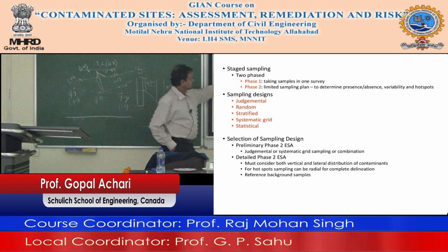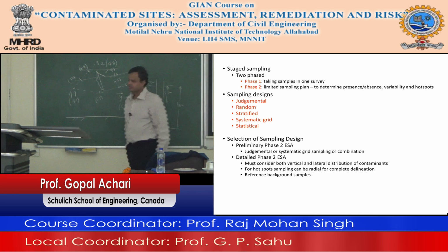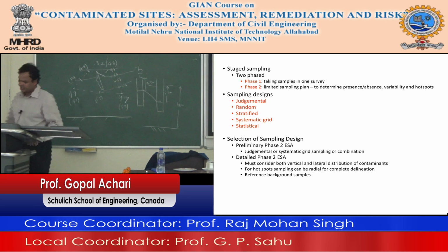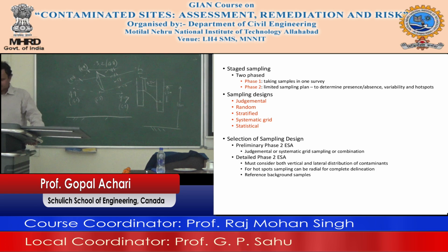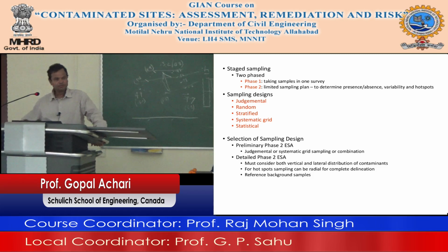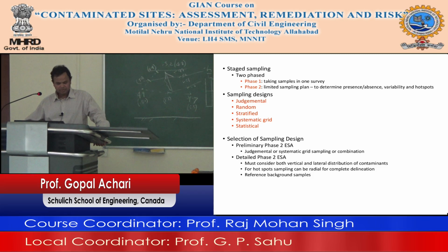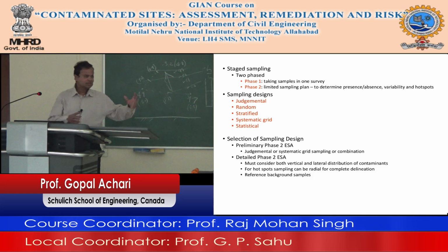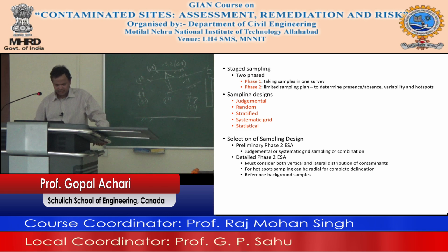It's not permitted for in situ characterization. It can be used as an initial screen in uniform areas and cannot be used for delineation of volatiles. With a composite sample, because you mix this, volatiles will go away by the time you actually get the compositing done. You're mixing it well, the volatiles will volatilize away. And it cannot be used for confirmatory sampling.